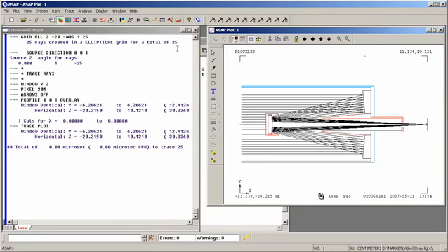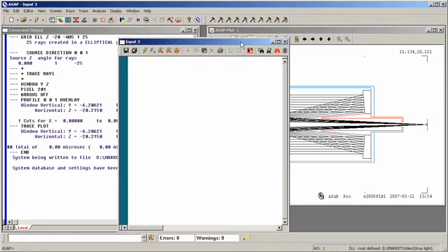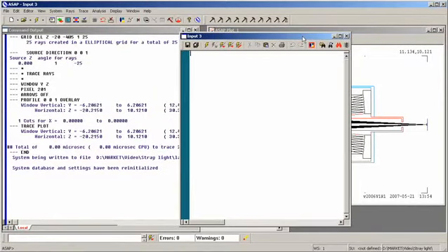How should we do this? Well, we issue the end command, or we hit the end button, telling ASAP I'm going to start again, and now going to create a file in ASAP to do this stray light analysis. In practice, doing stray light is typically done with scripts. Stray light analysis is complex enough that it's very difficult to do in a GUI environment.